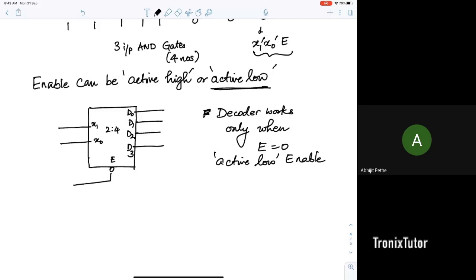Saransha, shouldn't we have an enable out? So that we'll talk about in the next class. Saksham, can enable be ANDed with outputs for us to know whether it is enabled? Yes, that's how you will implement this. Inside the chip, the enable is implemented in the AND function. This expression tells you that the enable is included in the AND. So this enable is going to kill the output if it's a 0, and will only give the valid output when enable is a 1. Because when enable is a 1, the AND can be thought of as just the min term.